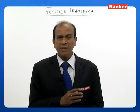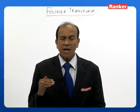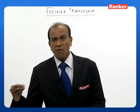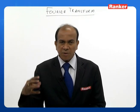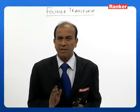Similarly, I take a power signal where limit T tends to infinity 1 by 2T integral minus T to plus T mod g of t whole square dt, you will get the power of the signal. So if I take the Fourier transform of this, I will get a Fourier spectrum for this called spectral density. Now when I calculate the area under the spectrum curve, then I will get the average power of the signal. So this is the concept of spectral densities.